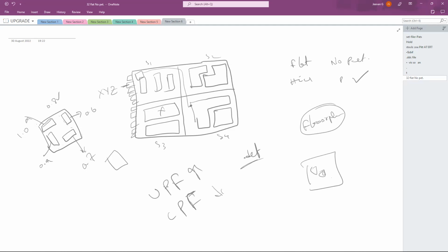What are the cells in the respective voltage area, what combination of cells you are seeing, and what is the voltage of this particular voltage area. Which is the positive supply and which is the ground supply for this particular voltage area. This is how the information will look in the UPF.